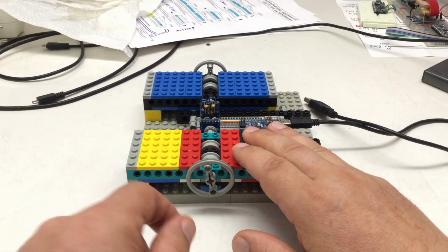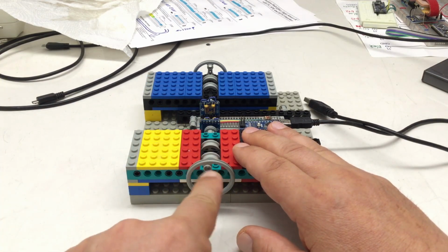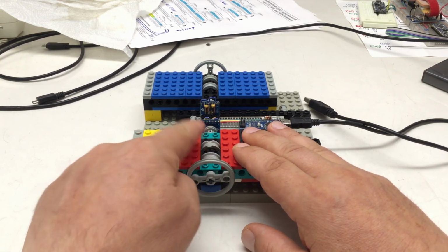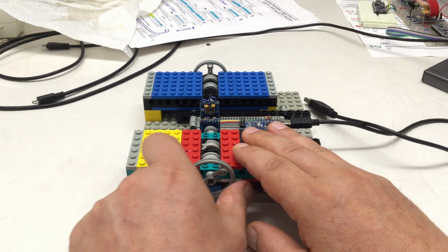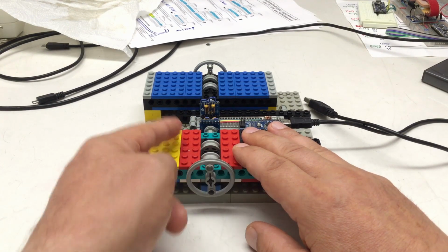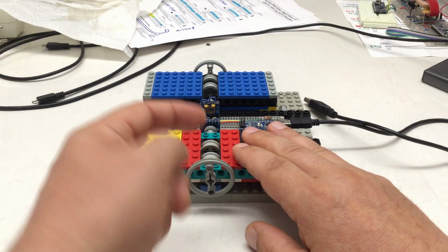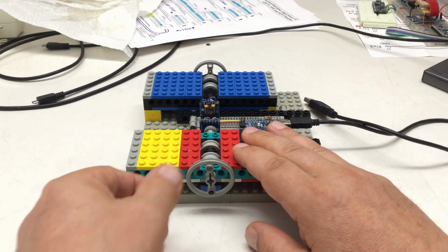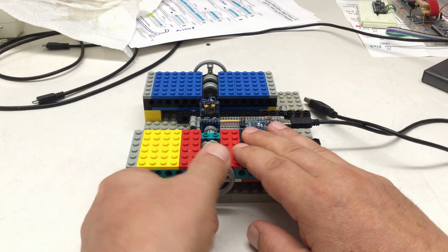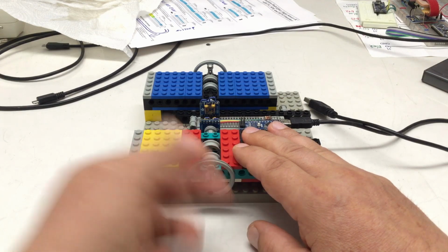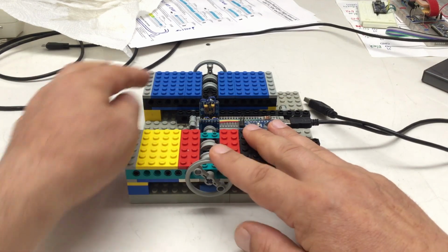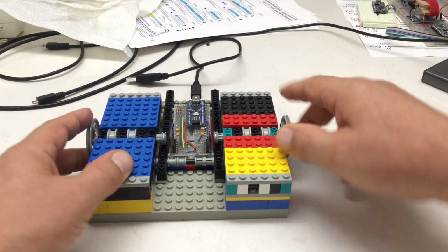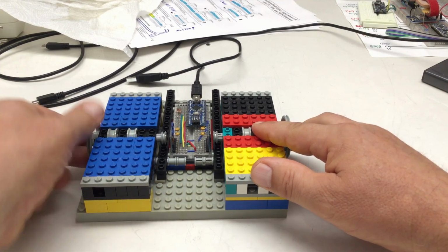And these first steps were: 1, setting a 0 position for our angle measurement. I've built in here a very distinctive detent giving us a mechanical 0 position. So that mechanical 0 position actually delivers us a 0 output of our angle measurement. And second, setting the direction of rotation. That is, the angle for both sides increases when I turn the wheels away, or the axis away from me.